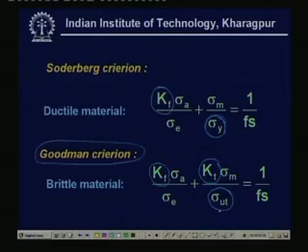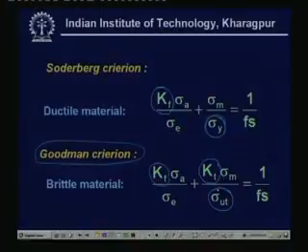The reason is that this theoretical stress concentration factor, as we have seen earlier, is a very localized phenomenon, and in the case of a ductile material, due to the stress concentration effect, even if it is at a higher stress, it gets locally stress relieved and does not affect the material to the extent it affects a brittle material.